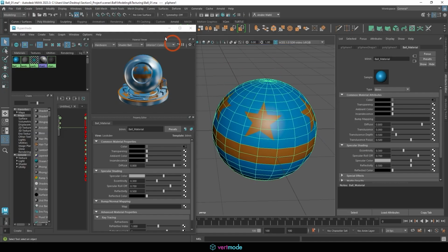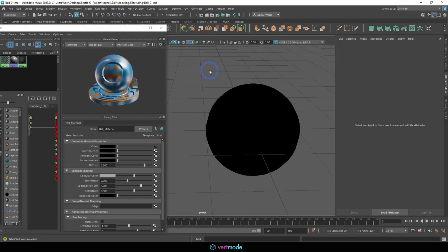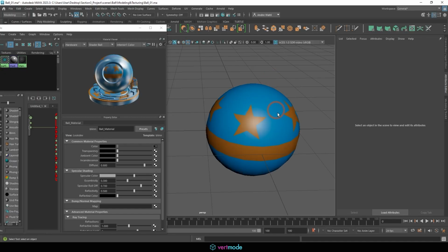Now, when we talk about the silhouette of an object, if you just turn the lights on with no lights in the scene, the silhouette is the outline of the object. So a very small bump on the star or on the stripe, we wouldn't see that necessarily because of how small it is relative to the object. Now, if we were an ant crawling on the surface, absolutely, in which case we'd have to model it. But if that's not the type of animation we're creating, then by no means do we need to do that. So I'm going to turn my lights back on, and let's hop over here and talk about a bump map.